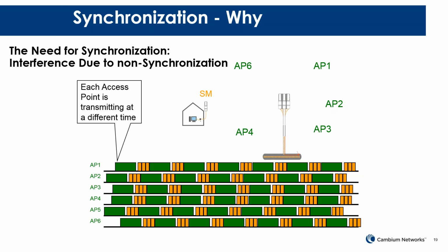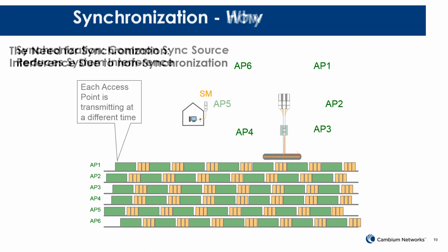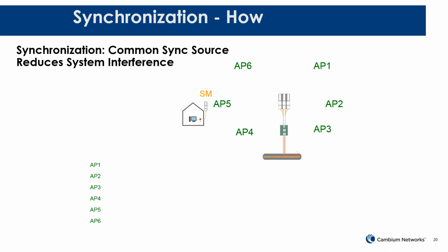And when they overlap on top of each other, they are basically causing interference to each other because they're co-located and they're very loud, screaming. Somebody's mouth is screaming very loudly into somebody's neighboring ear. That doesn't work in human terms. It doesn't work in radio terms, no matter how well you build the receivers.